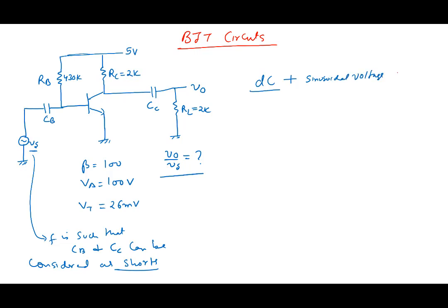So we will calculate the output. We do DC analysis to figure out IC, the DC current, base current, and DC voltages, all these DC quantities.